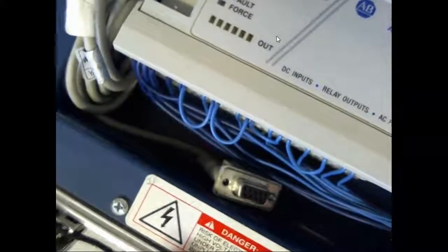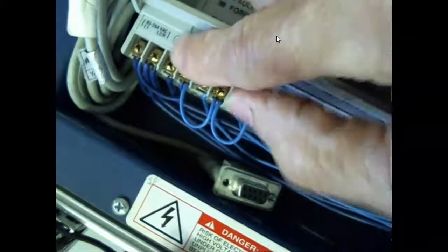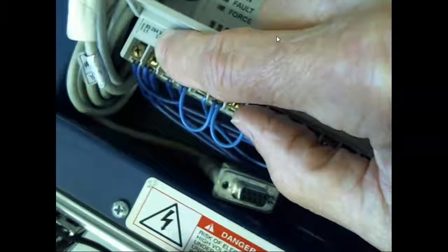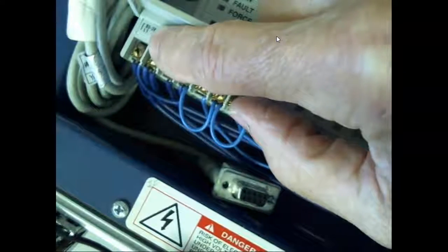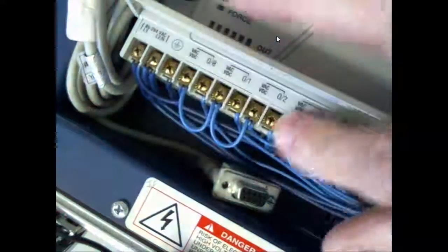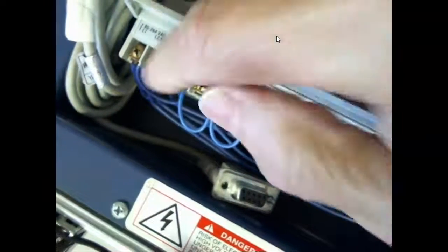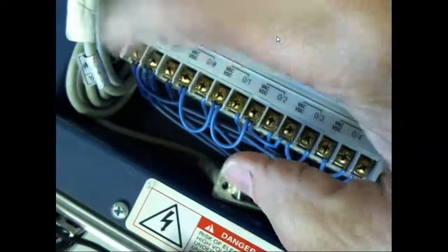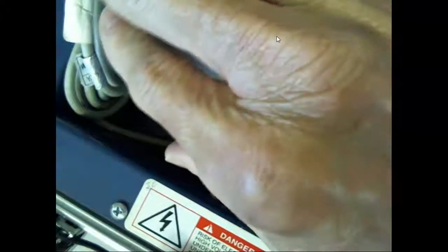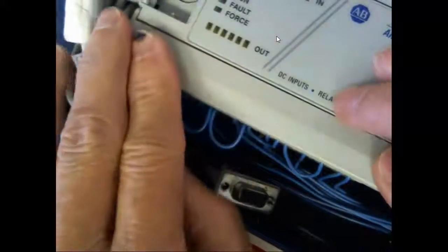And you can see it's jumping all the way down the line. And this is where the power supply is actually wired. This is 120. We can put between 85 and 254 volts in here. And then we take what we call L2, which is considered to be the common, and it's run all the way down here. So guys, these outputs output 120 volts. So when you're down there, I don't want to see this cover opened up, right? Makes sense.